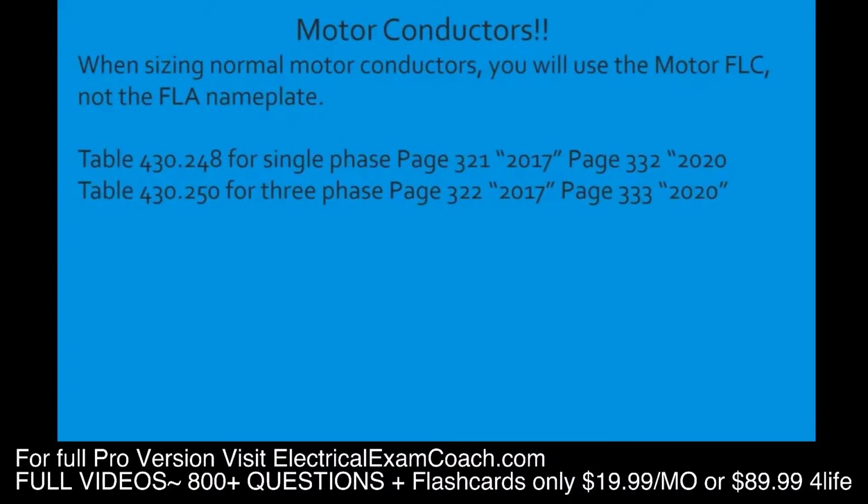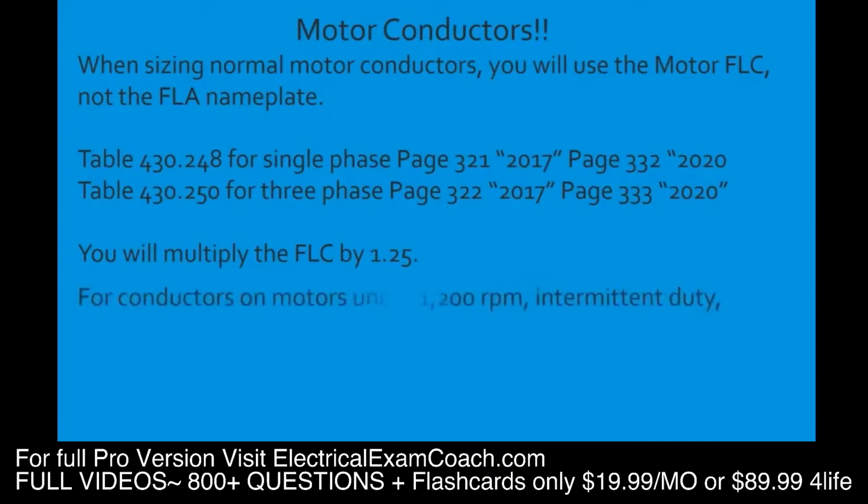Now let's learn about some more ground rules for motors. You're going to multiply the FLC by 125%. They consider motors continuous duty. Remember how we learned about continuous load and continuous duty previously? Well, it's the same thing. They're assuming that all motors are continuous duty, except, remember, this is the National Electrical Code, when you're dealing with certain circumstances.